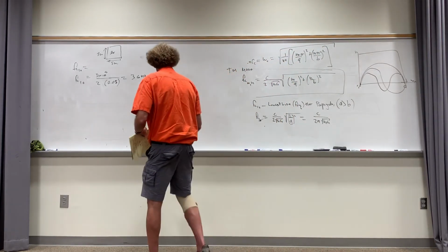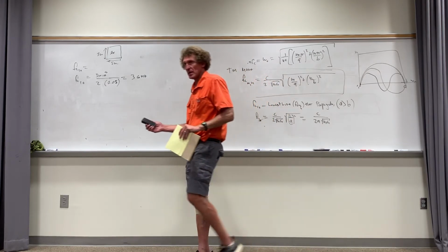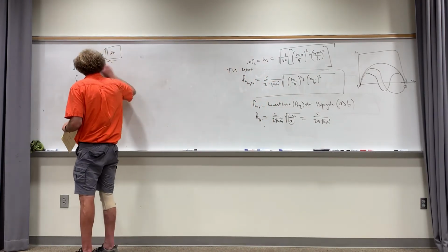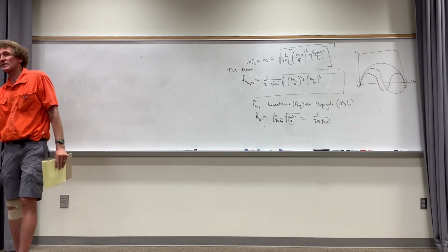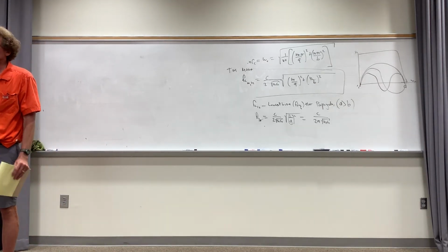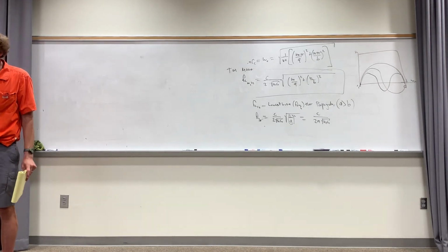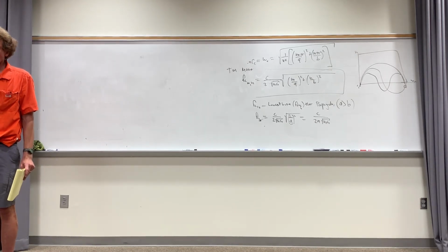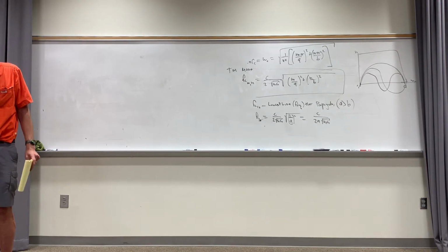This is waveguides. You see, this is quite a bit different than a transmission line. Here, your electric field of transmission line always was what? Magnetic and electric field was always transverse or perpendicular to the direction of propagation, right? The E field was between the inner core and the outer shield, right? That's the way it was pointed. And the H field was also in that plane, right? It was in the theta direction. There was nothing in the Z direction.